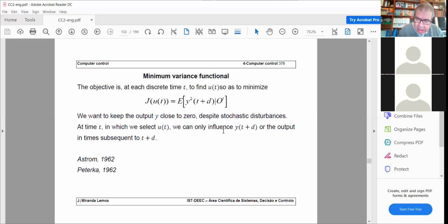The fact that here we have the output variable, and in the other case, we have a state, it's immaterial. Okay, the big difference comes from the fact that in the LQ controller, in the linear quadratic controller, you are considering an infinite horizon. Okay, and I told you that in the infinite horizon, the resulting controller stabilizes your system.